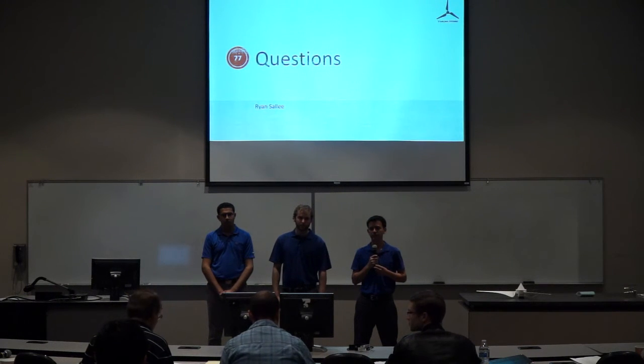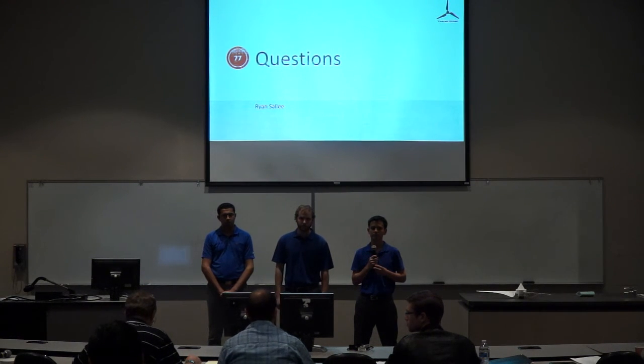The other big thing to me is the structural analysis. You've printed your parts but haven't done the structural analysis. I don't know anything about the strength of 3D printed material, but do you have an idea of the force you're expecting, say at the connection, or the overturning force of the thing, or have you done that work?